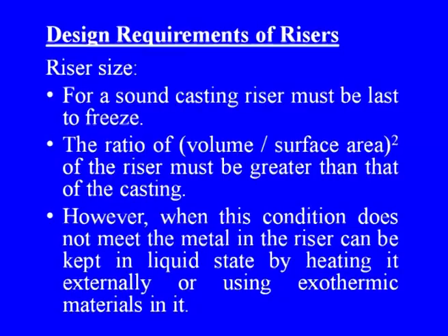Now, what are the design requirements of risers? First is the riser size. For a sound casting, the riser must be the last to freeze. The ratio of volume to surface area of the riser must be greater than that of the casting. However, when this condition is not met, the metal in the riser can be kept in liquid state by heating it externally or using exothermic materials in it.